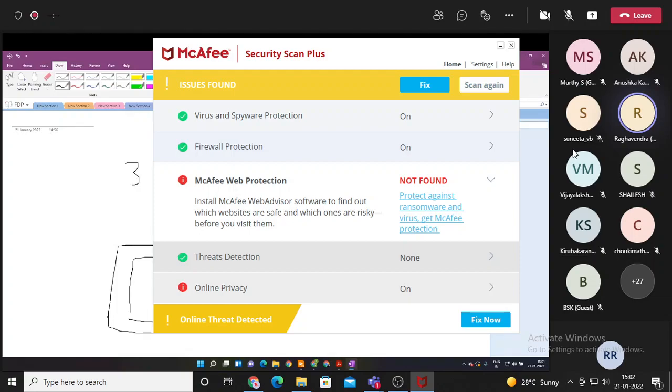So the daughter board that we have used, specifically for this particular application, is a daughter board that does not have any mixers. It does not have any filters. It only has a low pass filter over here. There are no band pass filters. There are no amplifiers. There are no mixers. Nothing is there. You directly take data from the DAC and then give it to this filter. After this, you just have a port, an SMA port.